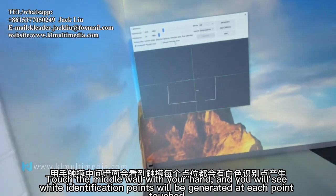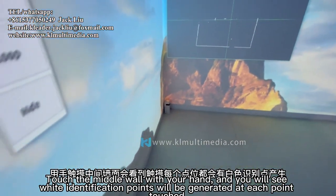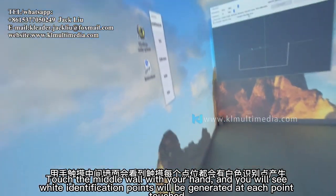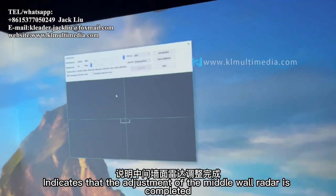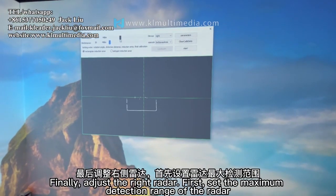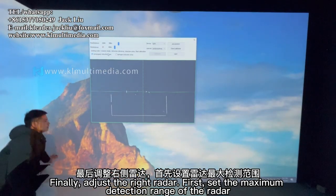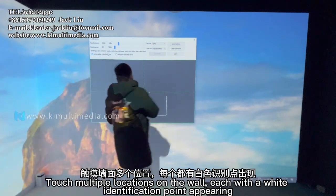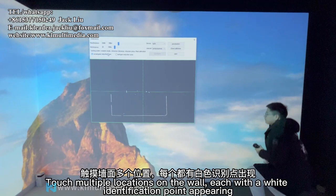Touch the middle wall with your hand and you will see white identification points generated at each point touched. This indicates that the adjustment of the middle wall radar is completed. Finally, adjust the right radar. First, set the maximum detection range of the radar. Touch multiple locations on the wall, each with a white identification point appearing.